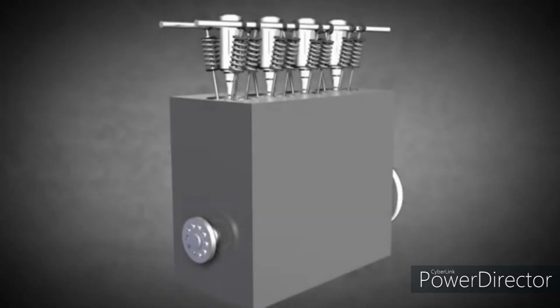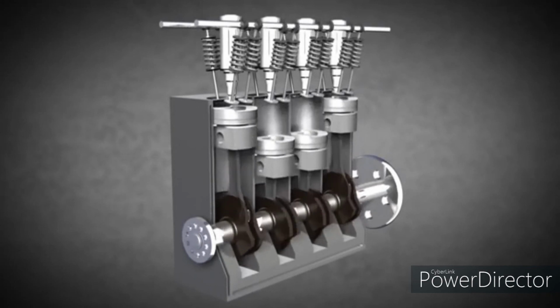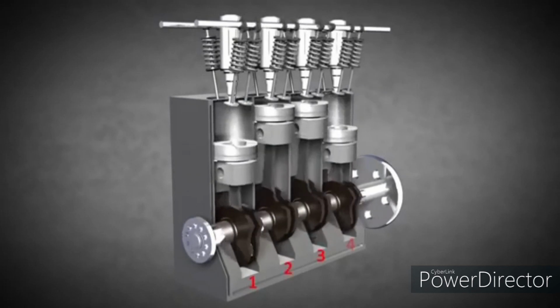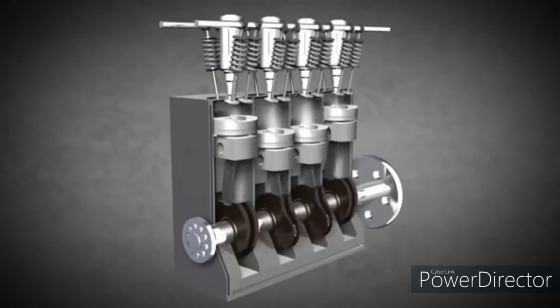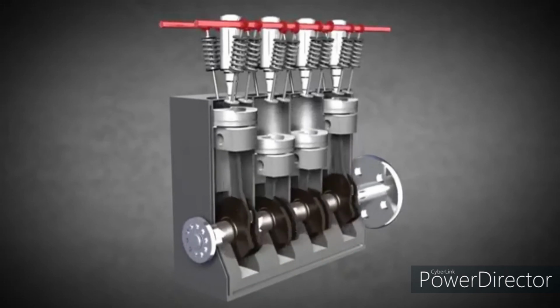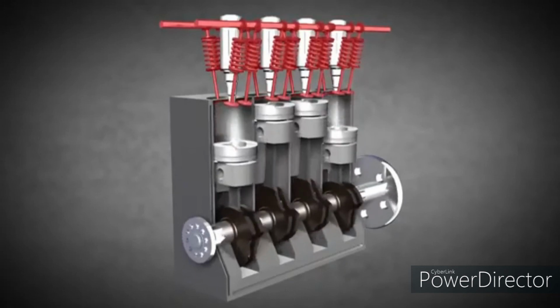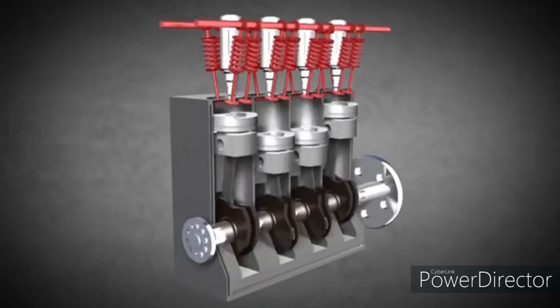Diesel engines were established in 1893 by inventor Rudolf Diesel. This animation describes the working principles of diesel engines in the context of an inline-4 engine that operates in a 4-stroke mode. This kind of engine has 4 cylinders mounted in a straight line. The camshafts operate the valves. In this animation, each cylinder has 4 valves, of which 2 are inlet valves and 2 are outlet valves.